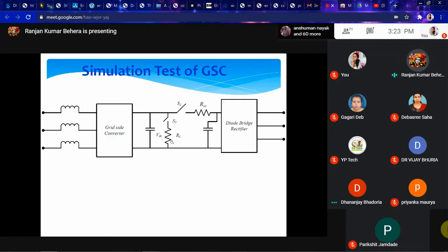So to understand the bidirectional power flow, the power can flow in bidirectional. So what we do, we use an auto transformer. We have a 3-phase bridge. Then we have a filter. Then we feed this through a resistance to charge this capacitor S1. And to dissipate in the resistance, that is by turning on S1 and S2.